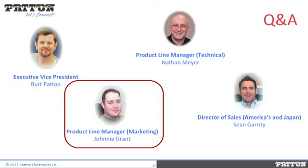All right, another one came in here. This one asks, what line coding methods are you using? The beauty of Patton Electronics is we have many choices of modulation schemes to use on our Ethernet extenders. We really choose the modulation scheme based on the application. For our long-range product line, we use TC-PAM. For our short-range, high-speed, we've used various different technologies. The one in our latest high-speed Ethernet extender is using DMT.